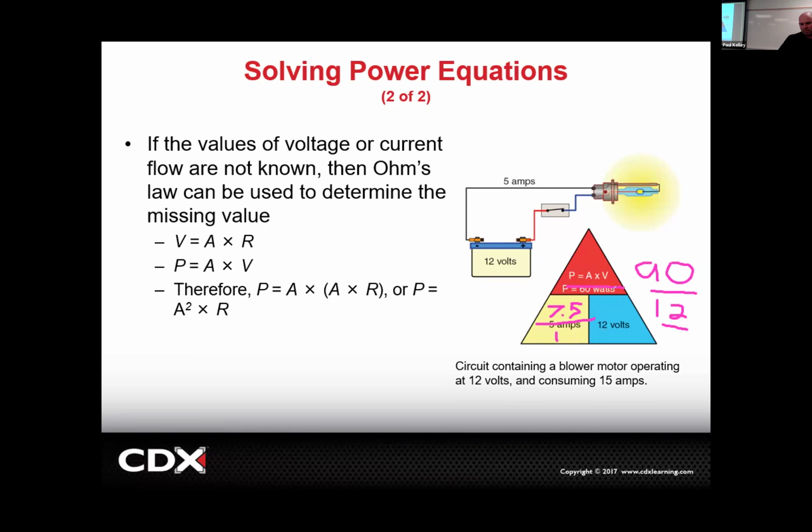So if it were me and the bulbs weren't bright enough, I'd probably lean towards an LED, simply because it's going to lower your amps. And to me, the less amps, the better. The less amps we can flow, the better. It's just more efficient and everything. So all my stuff that I want brighter bulbs for has LEDs. Cool lesson. So if you think about that, if the LED has less amps, therefore the LED must have much higher resistance, and they do. FYI.